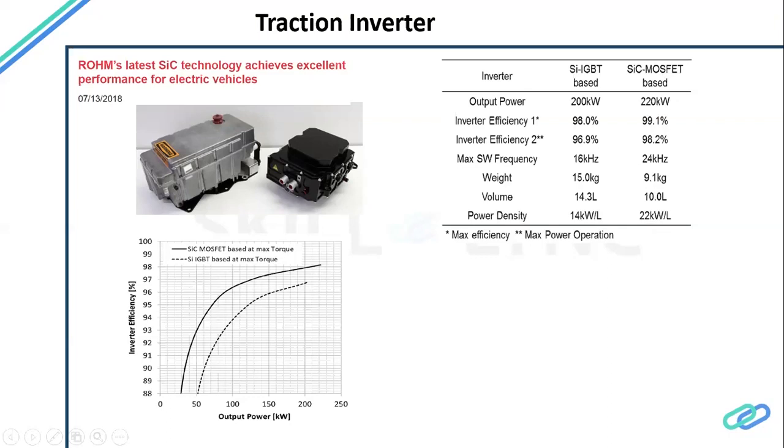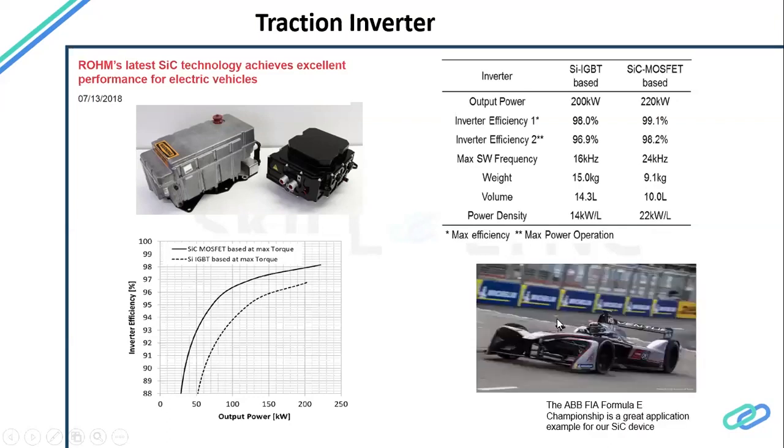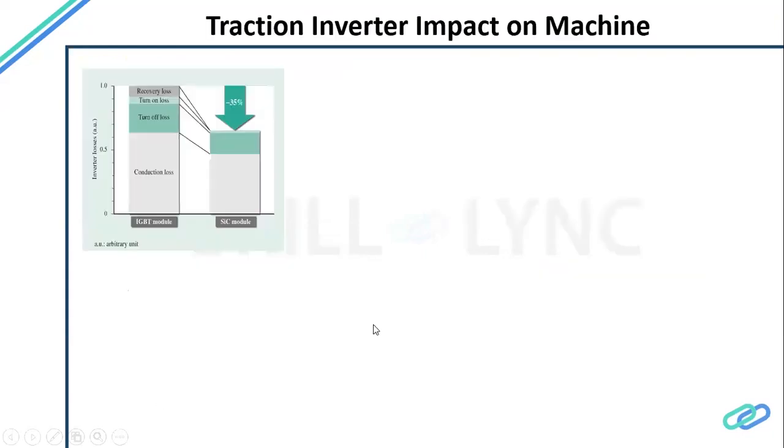on silicon carbide MOSFETs, and some of these are deployed also. You can see there are many tier one suppliers claiming that we have this already in place for inverter and converter, and those are commercially available. It's no more just university-level research, but it has all been brought to the factory now from university. Those give a lot of benefits because the conduction losses and the switching losses, which are predominant, are very, very low. They are much more thermally stable.